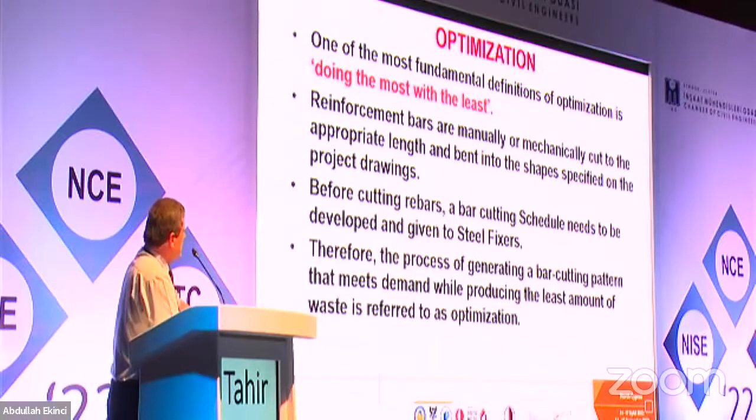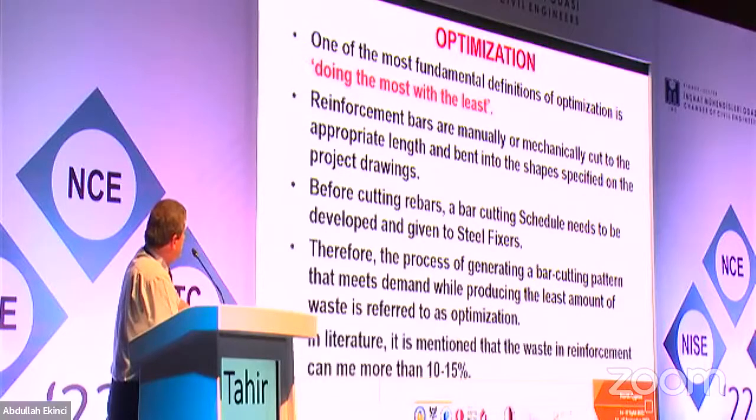Therefore, the process of generating a bar cutting pattern that meets demand while producing the least amount of waste is referred to as optimization. In the literature, it is mentioned that the waste in reinforcement can be more than 10 to 15%, more than that.